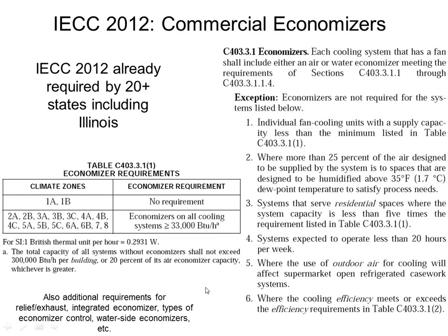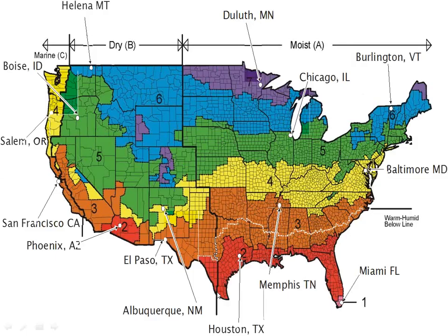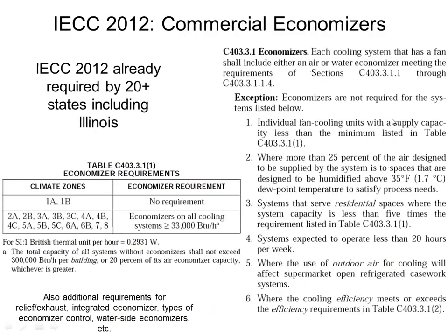Right? If you got a water side economizer because it's a big hydronic job, then that could be your way of getting the economizer. It doesn't have to be air side. This is the climate zone map. We're going to use this several times throughout the different topics today and next week. Right? But where I'm standing at right here in the Illinois area, I'm in climate zone 5, which is green. And I am to the right half of the country, which is the moist half. So I am 5A, right? If I go back one over there in the table over there, 5A, that includes me, right?